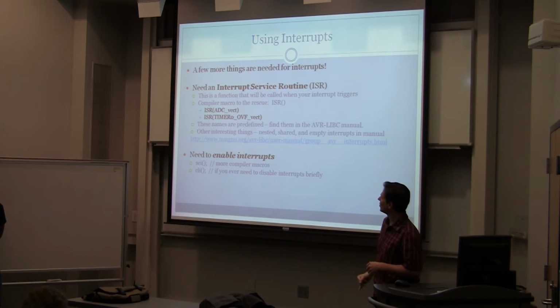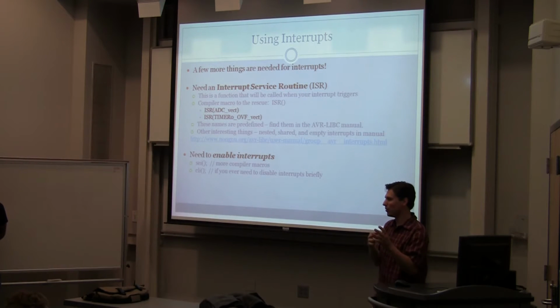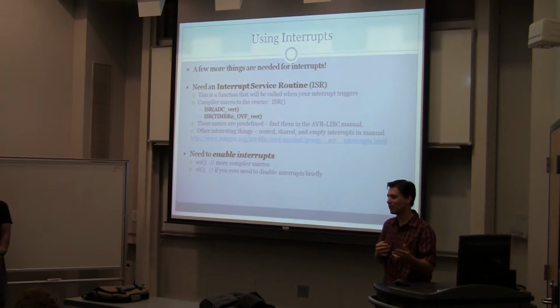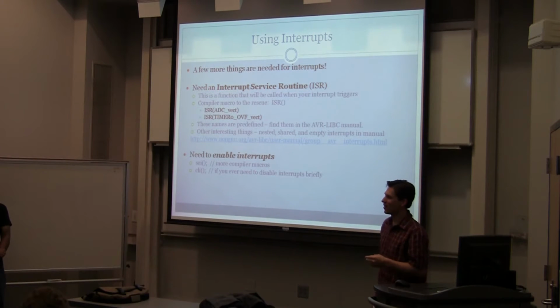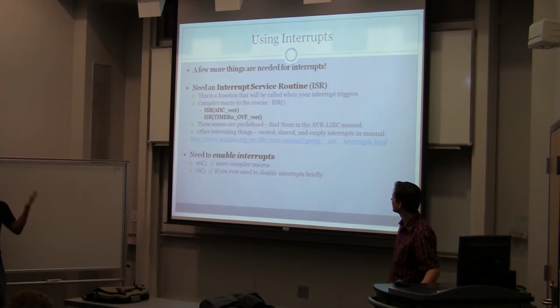If you don't have one of those, your Tiny throws an interrupt, but it's not serviced. And what happens if it's not serviced is it goes to a default vector. It sets it to all zeros. That default vector is a reset vector, which just resets your program. So by not creating an ISR, you get this situation where you turn on your gadget and it's just constantly resetting. Not a good thing. By default, the reset vector is for your main function, which is usually not quite what you wanted.